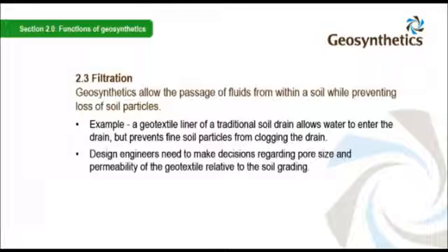The traditional system involves layers of graded aggregate, which filters the soil particles out as the water passes through, but a geosynthetic layer performs the same function in a simple way at a reduced cost.